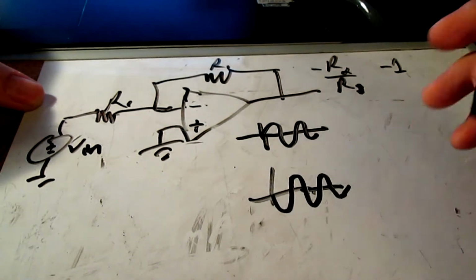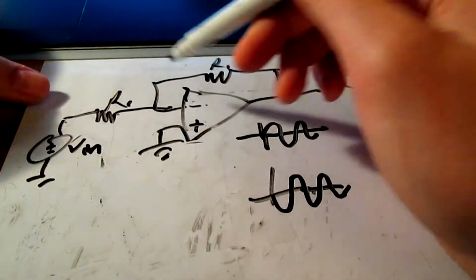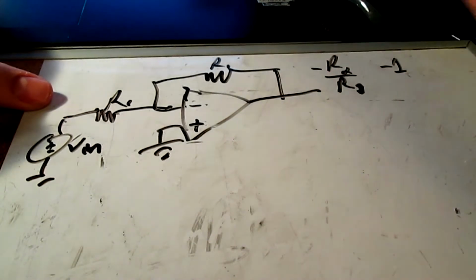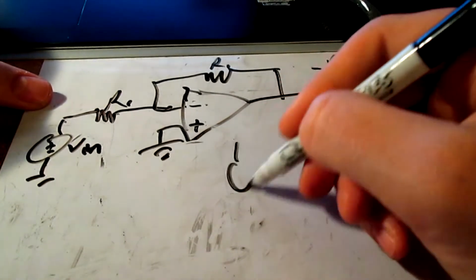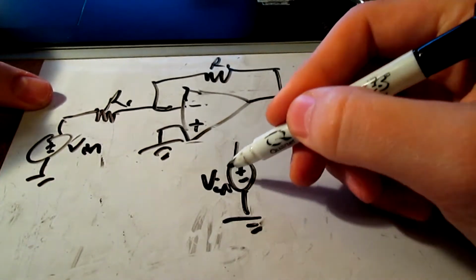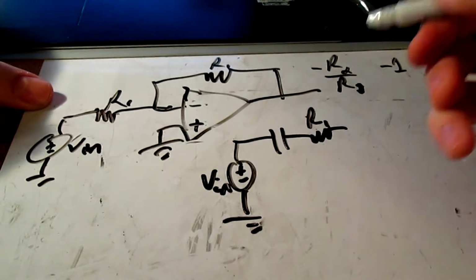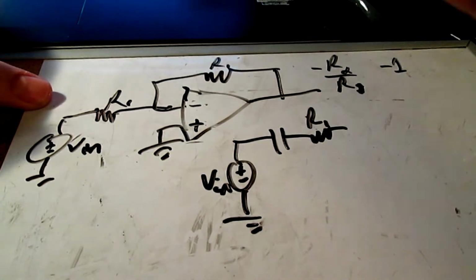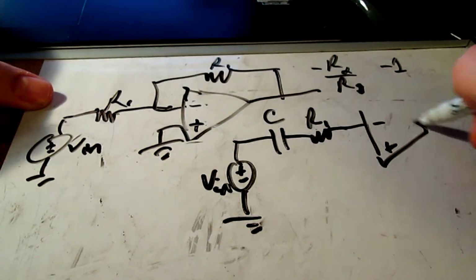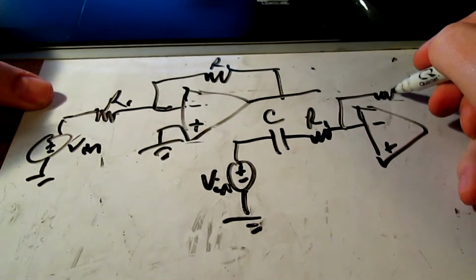Okay? Now this looks very familiar. Just familiarize yourself from the high pass that I just showed you to an operational amplifier, and we can do the same in one stage. So we have our VN, and we're just going to do the same thing. Here is a high pass filter that also amplifies your signal. So I wanted a gain of 10, so this will be 10R1.